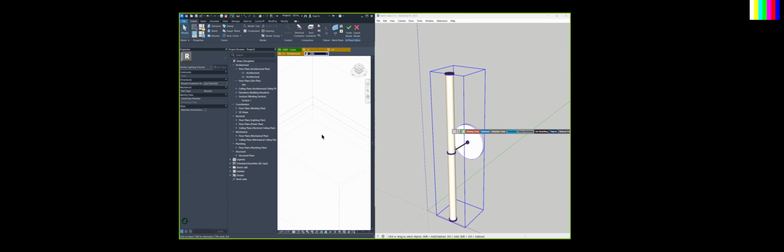Now it's in the sketch mode. So this is where you would normally go to extrude and model the thing that you want to build. Maybe it's something that you want to build from scratch or whatever. But in this case, I don't want to build something. Instead, I'm going to go to manage and I'm going to link it while I'm in model in place, right?